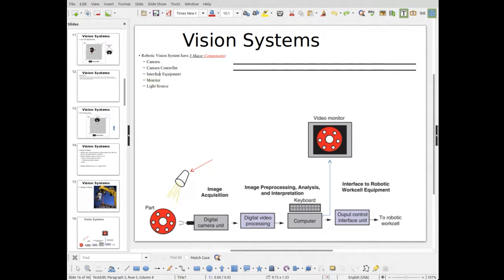Once the part is taught, then the controller, whether it's a PLC controller or the controller of the robot itself, is actually going to take the picture, do the comparisons, and do the math to figure out the X, Y, yaw, pitch, and roll, and all those different things.